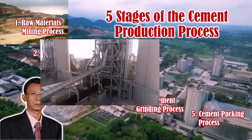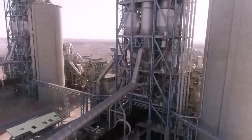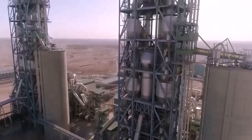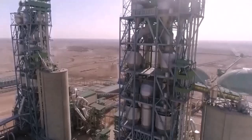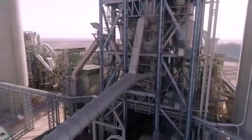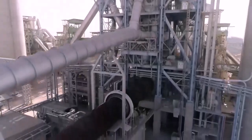Three, burning and cooling process. In this combustion process, the feed material undergoes several chemical and physical reactions, until it forms clinker. The raw meal kiln feed is heated in a preheater tower, where the initial drying reaction occurs at temperatures of 100 to 300 degrees Celsius.